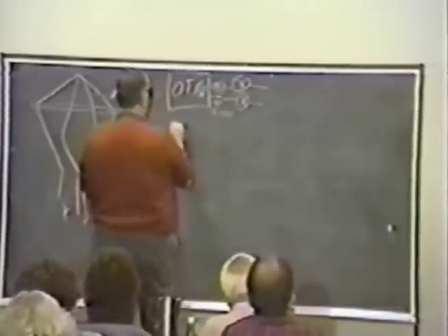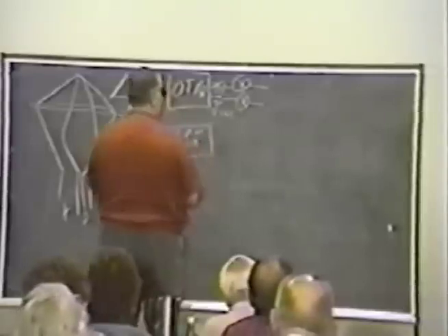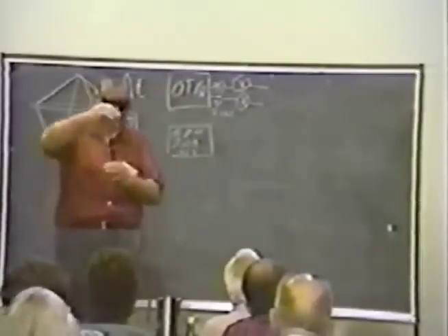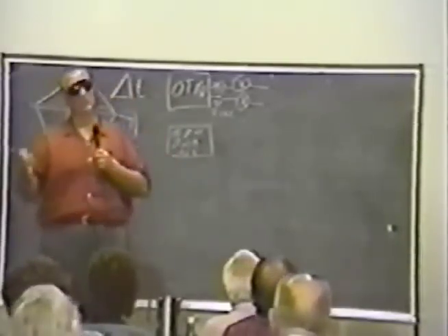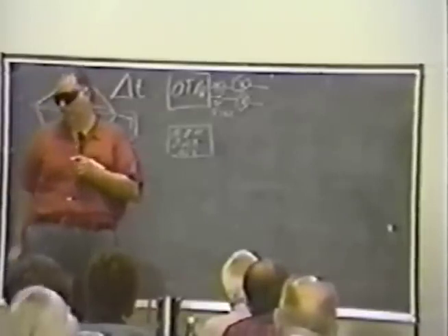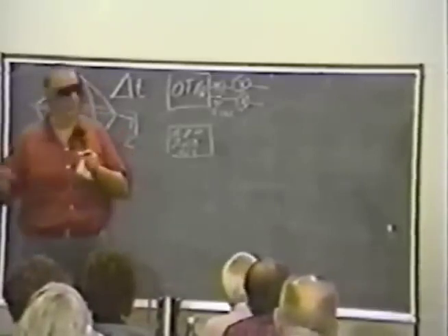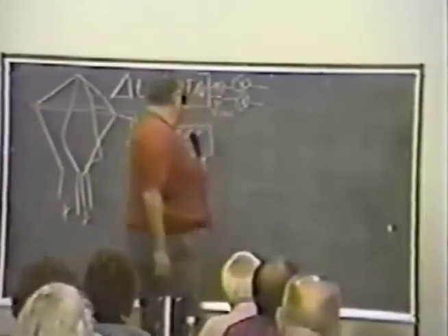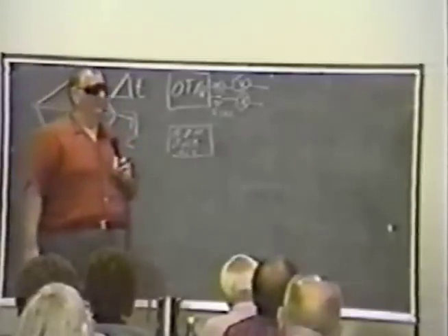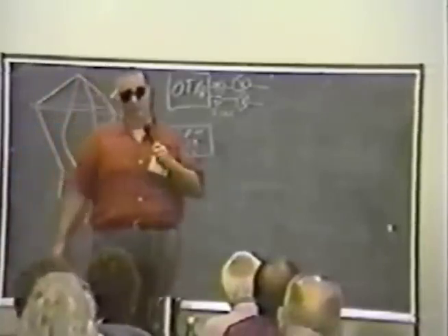Now, we take our white noise generator, our General Radio. I think it's an 1863, if I recall, which is a little box about that big that has a Gaussian noise tube in it and 2 6AQ5 amplifiers with its levels and a level control meter for its output, has bandwidth limitations. This thing can go to 500 kilohertz bandwidth or 20 kilohertz, or I think it's 5 megahertz also. Get the old GR catalog and look up their Gaussian noise source. This thing, General Radio, is available on the surplus market, a dime a dozen. General Radio must have made trillions of these things.